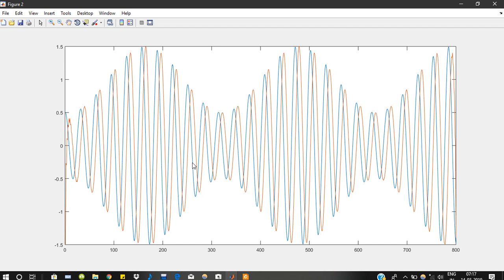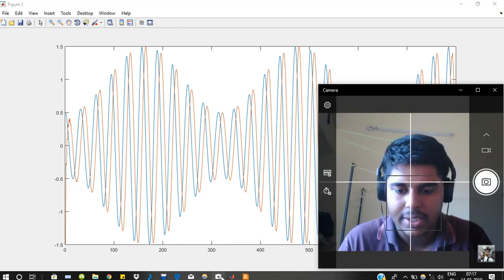To this time based sequence, you multiply the complex number j and make another complex variable z, which is your original signal plus j times the quadrature phase shifted signal, something like cos t plus j sin t. That way you create a complex number. The amplitude of the wave is simply the square root of the real part squared plus the imaginary part squared, which you can calculate like this.